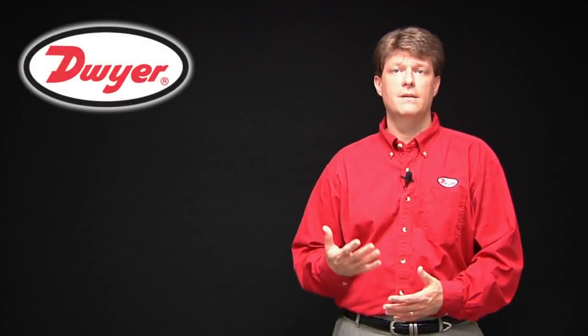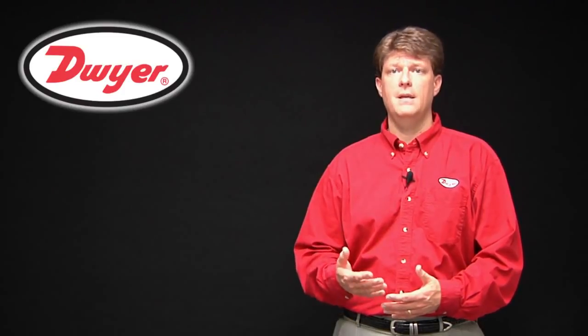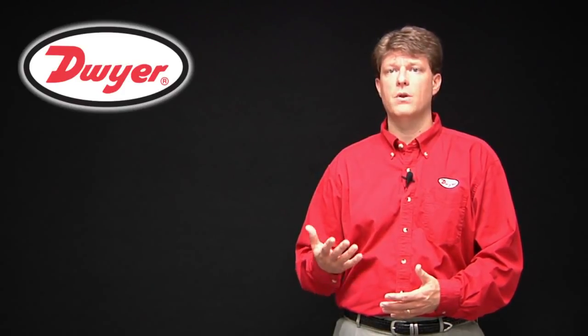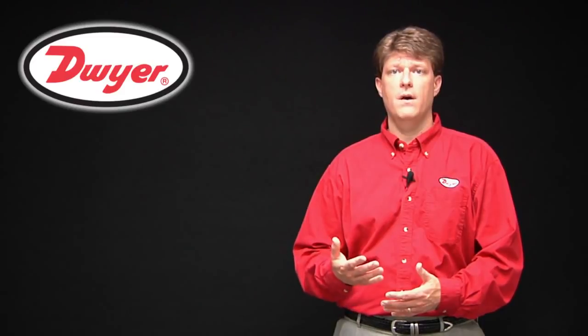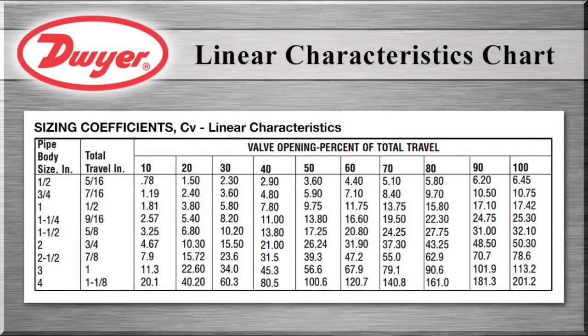Once the required CV is determined, selection of the proper size control valve can be obtained by comparing the calculated application required CV to the CV values for the high flow valves. To size properly, it is best to increase the required CV by 10 to 15% to account for different operating conditions. Also, the minimum required controllable flow should fall within the rangeability of the valve.